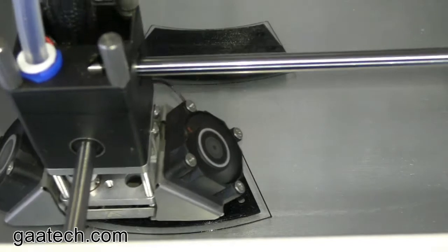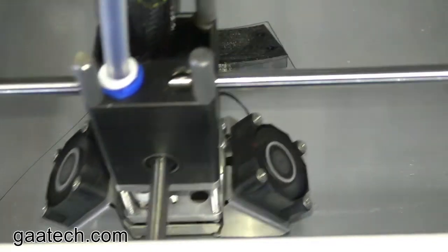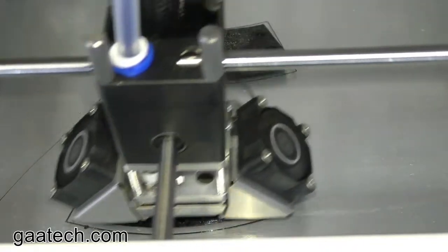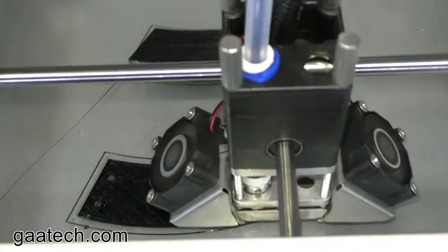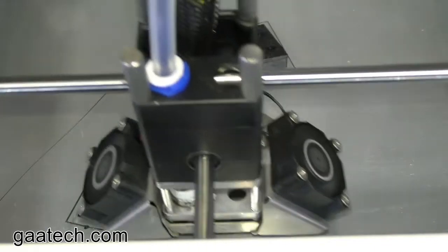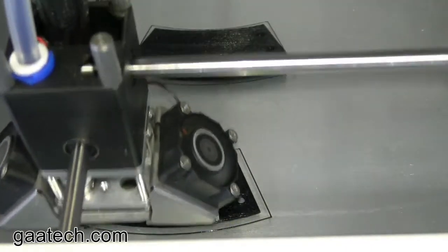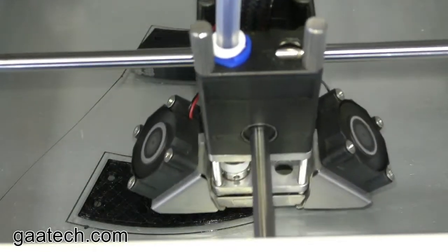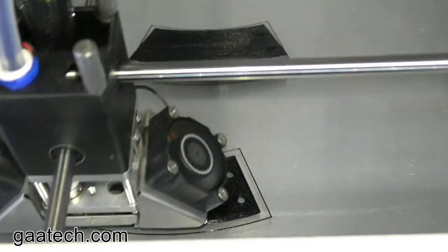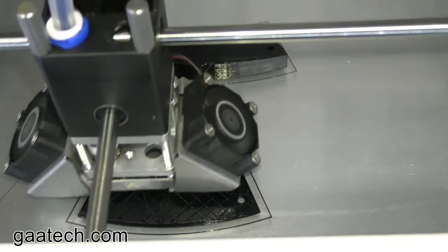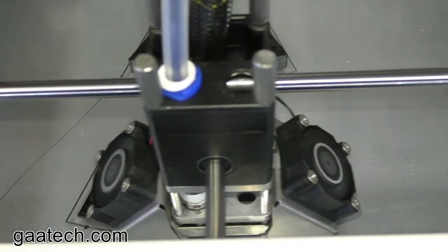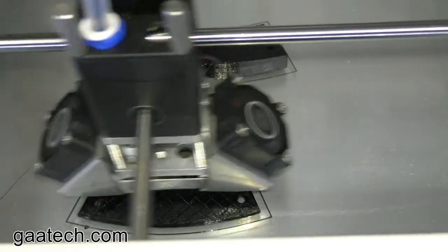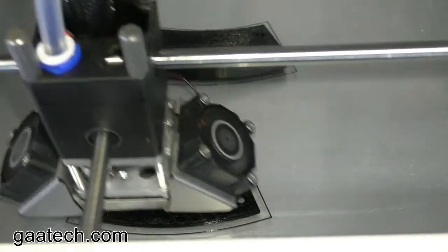Obviously the wall thickness is designed, and I can tell it how thick I want the walls to be printed, as well as the top and the bottom layers. So several things dictate how strong the parts are: how thick the base and the top are printed, how thick the walls are, and how dense the infill is.